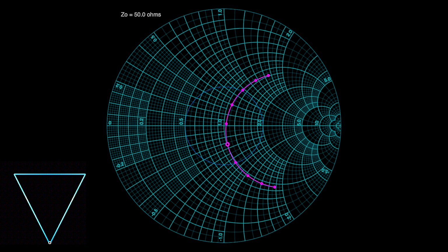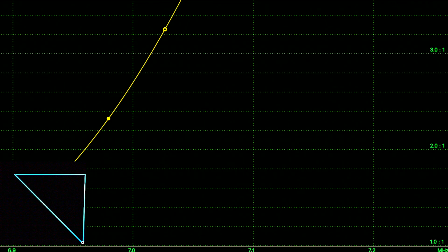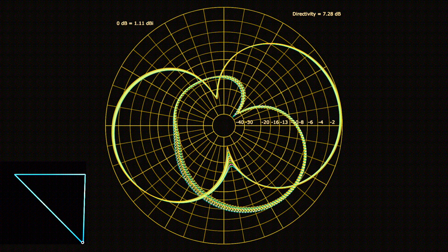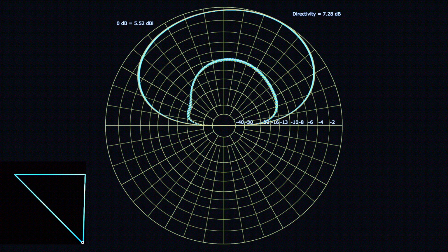We are gradually moving the feed point by 5 meters to the right. The current distribution remains the same along the circumference, but it is shifted according to the asymmetry. The impedance remains basically similar, but the resonance frequency is shifting downwards. The azimuth diagram rotates about 15 degrees counterclockwise, corresponding to the current's distribution. The elevation diagram remains almost the same. It just shows a growing vertical polarization, which is due to the rotation of the diagram.